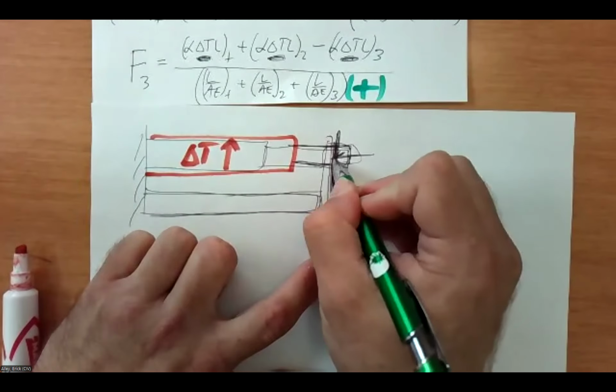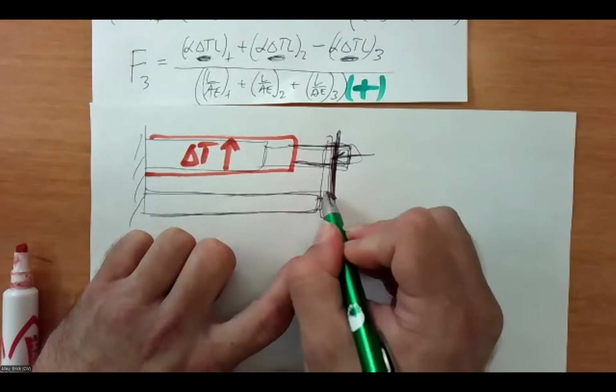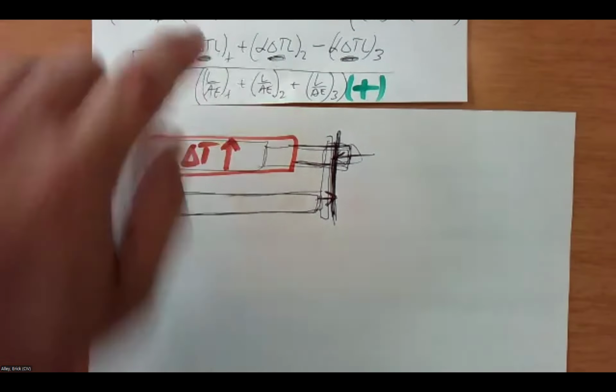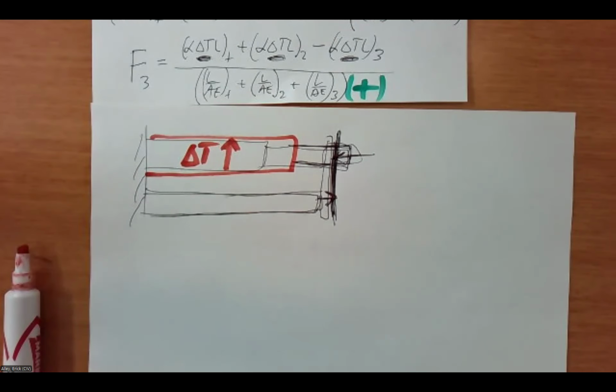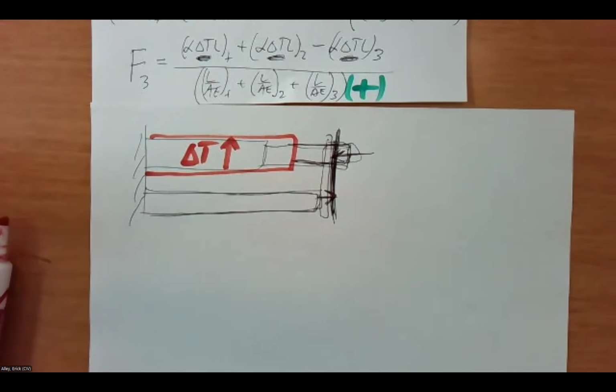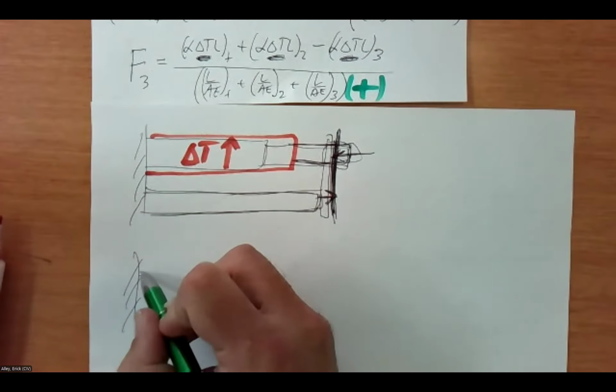I should have to push back on this top column and pull out on this bottom column to meet them together. And that's what this formula tells me. If I have just delta T1, I get a positive number in the top. And that means F3, as a formula, is going to be tension. And because F2 and F1 are just the negative of this, then that one would have to go in compression. So that passes the test okay. I could see also if I heated up number 2 by itself, same deal. Let's say we just heated up bar number 3.